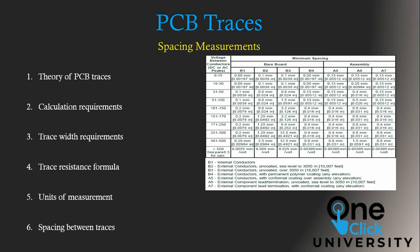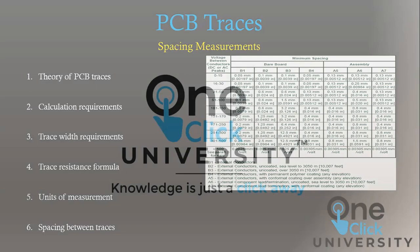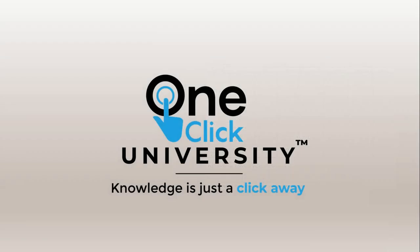But what about the spacing? The circuits are very small and it is not easy to determine the spacing between the traces. So keep the spaces between the traces such that the space is at least 75% of the width of the trace that is being used, or keep it a common 6 to 30 mils, which depends on the amount of current flowing through the circuit. So that's all about the width, the spacing and the theory of turns or bends in the PCB traces.